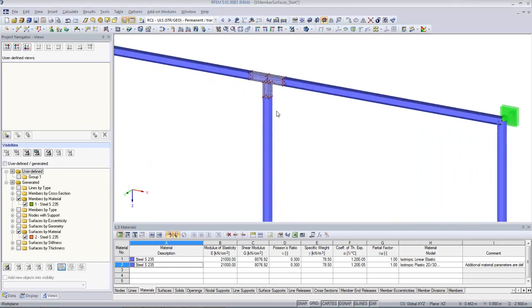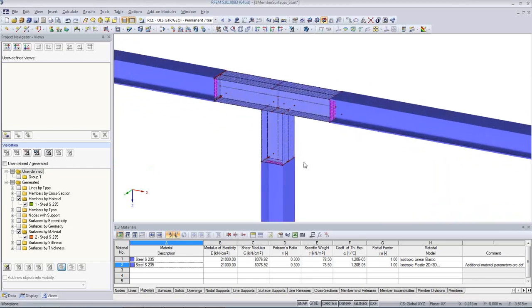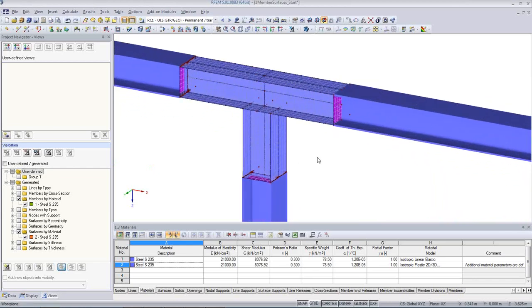First of all, I want to do something else. I forgot something. I also have now the option to, for example, change the thickness of an individual plate here. I can select it. Multi-selection is possible by pressing the Control or Shift key. I can rotate it. Actually, if you rotate it, you use the Alt key.